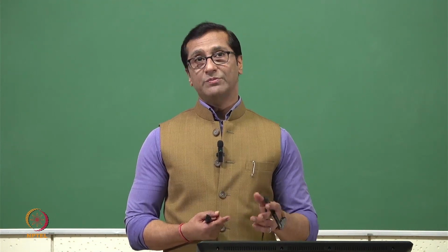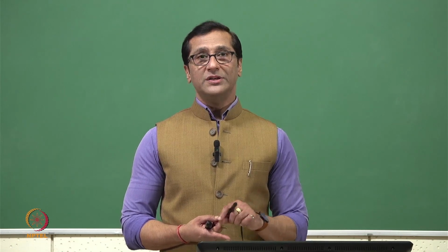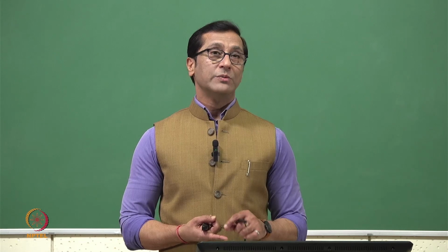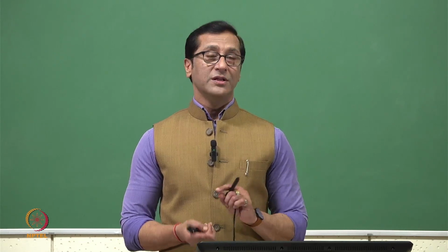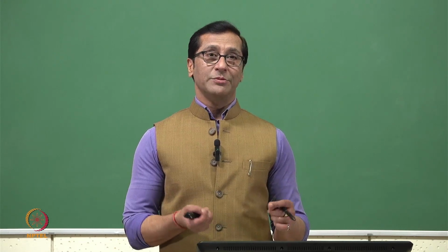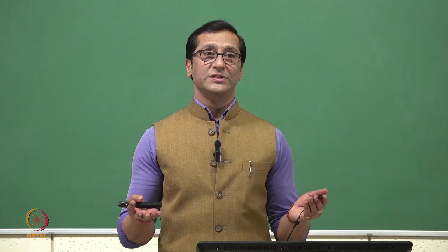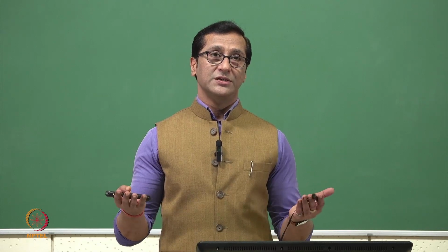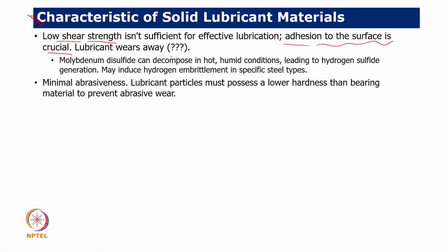On top of that, as I mentioned in the previous slide, there will be wear rate. So that wear rate also needs to be accounted for. So again, the tribology is becoming time dependent. Whatever I have designed initially may not be okay after 10 hours or 15 hours or 100 hours. That needs to be checked, because if a lubricant wears away, wear will be there.